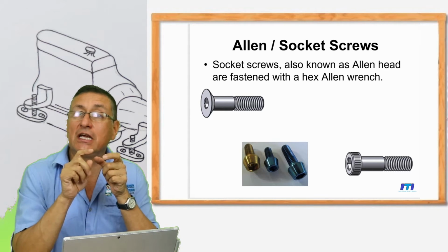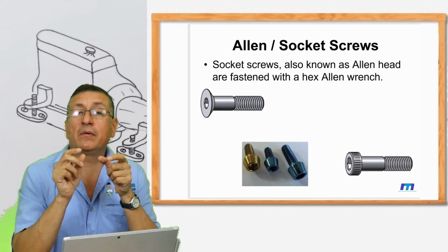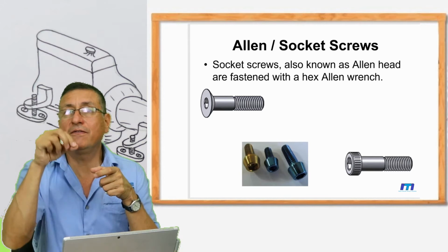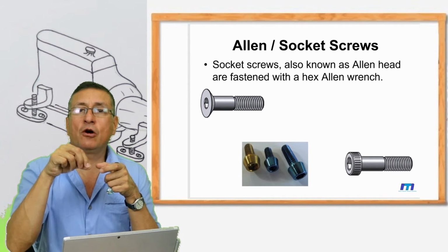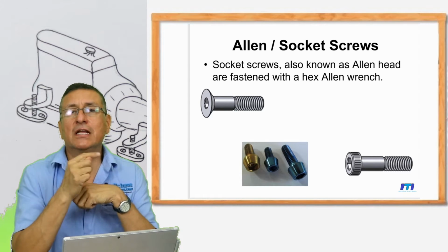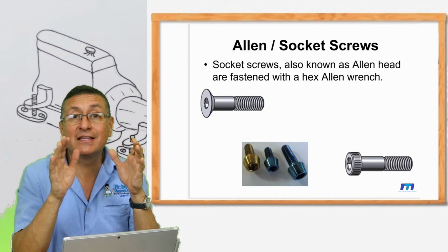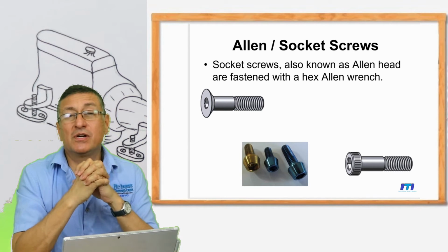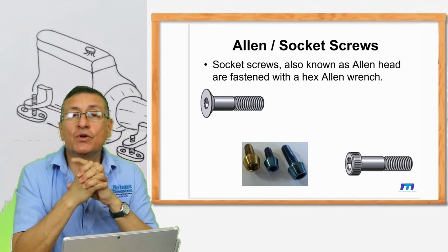You need to check in the other system. Probably if that Allen key is standard, probably the similar Allen key in metric fits it better. Oh yeah, no play. Be careful. If you have a little play, this is not the key for that bolt, and you damage the head. You damage the head of the bolt, and finito. You can spend weeks trying to remove one bolt.